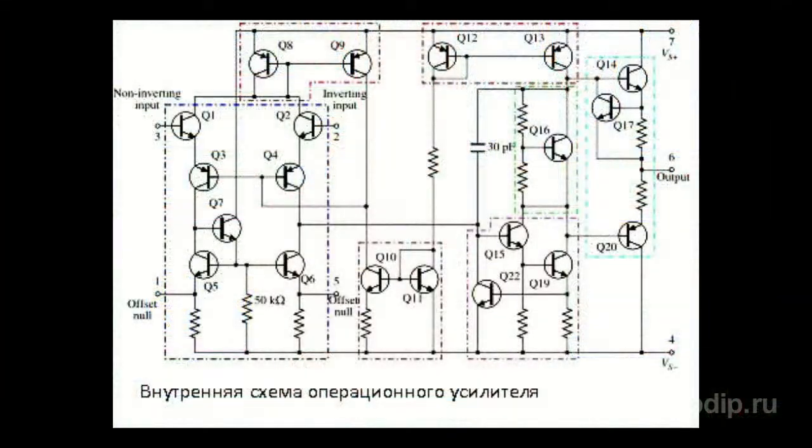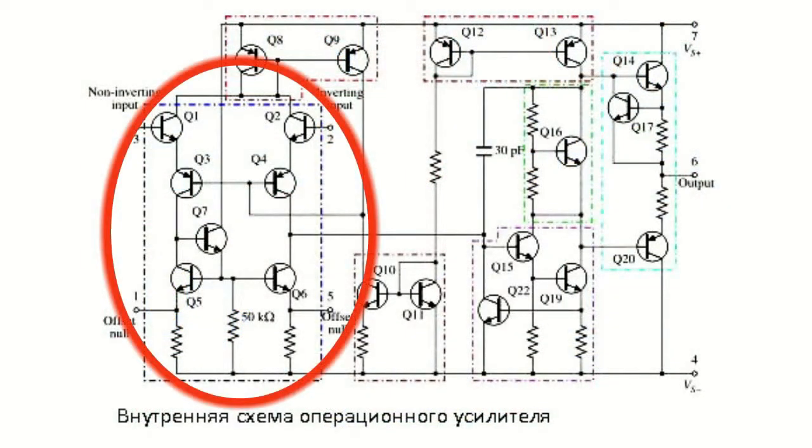Structures of various operational amplifiers differ from each other, but still are based on the same principle. Operational amplifiers consist of the following functional blocks. Differential amplifier, which provides amplification at low noise level and has a high input resistance. Usually it has a differential output.